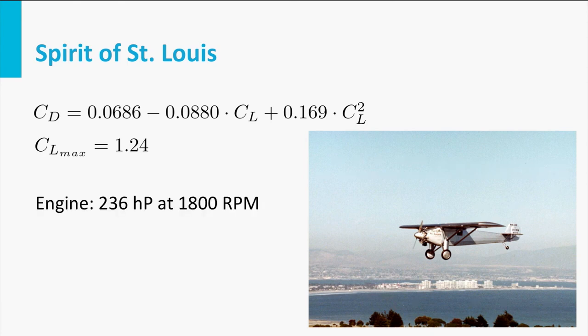Now let us start by making a performance diagram of this aircraft. The performance diagram of an aircraft is basically, on the y-axis, the power required, which is drag multiplied with airspeed, and on the horizontal axis it states the airspeed of the aircraft. Now we would like to calculate points in this graph and determine what the whole graph looks like.